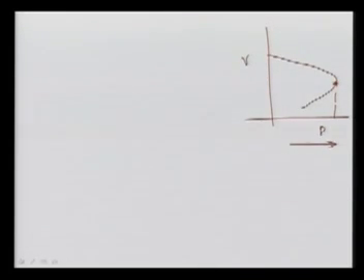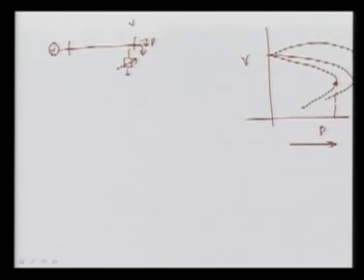Now if you are going to use compensators, let's suppose you have a generator, your transmission line, this is your load, and you are using a compensator here, that is a shunt compensator. Again, it may be your SVC or STATCOM, that is variable. So we can maintain the voltage at this bus. Let's suppose you are going for leading here, if you are injecting reactive power, this value will be like this, and it may be going this way. So this is leading power factor. If you observe lagging power factor here, then you can go for less loading.